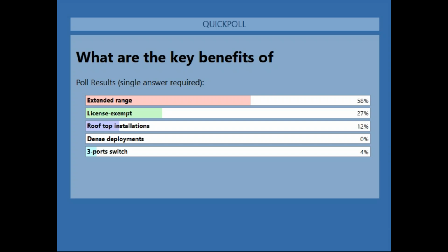For example, if you have started the network with 600s and now you want to continue and roll out 614s exclusively, and you also want to keep some spare radios, you are right in that case you could keep some 614s only. And if a link which has been deployed with 600s would see a failure on one side, you can put there a 614, set it up for the same channel as the other side, and it will work no problems at all.